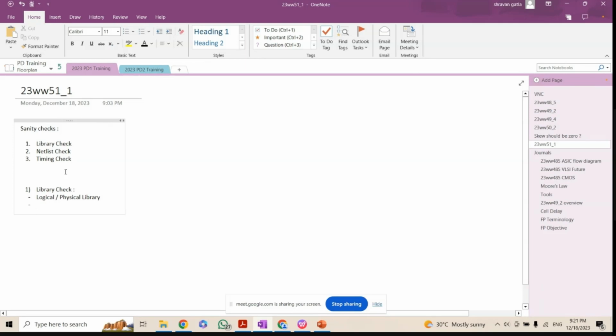So that is the reason we should not have floating inputs. Okay, then no multi-driven nets. If we have multi-driven nets, the input pin of the cell doesn't know which input it should pick. That's the reason. Maybe in a face-to-face interview, he may ask you to draw one example for multi-driven nets. So you need to draw like this.